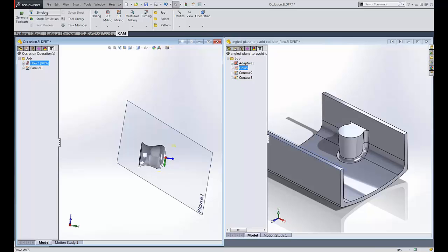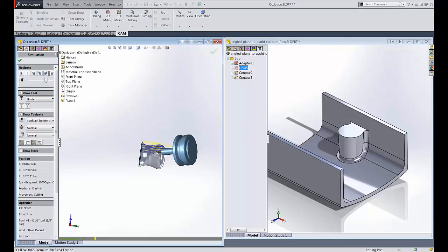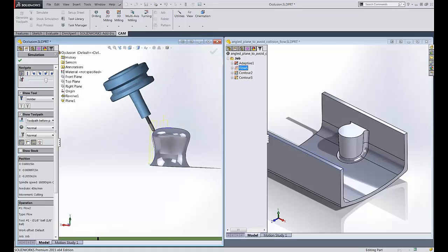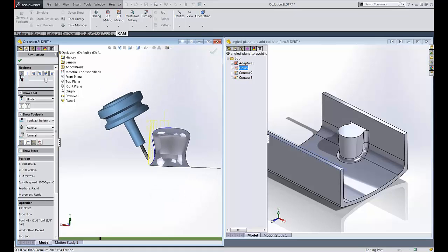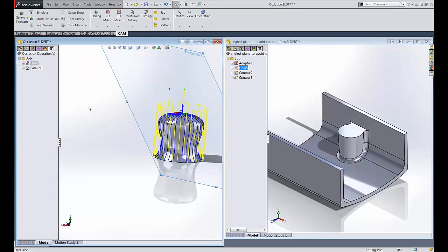We'll try and hit the minimum amount that we need here rather than just some. Yeah, there you go. So that's much better. It's tilted enough to keep the tool holder out of the way. It's tilted enough to keep the shank off, and it minimizes motion. So that's probably enough time spent on that one.